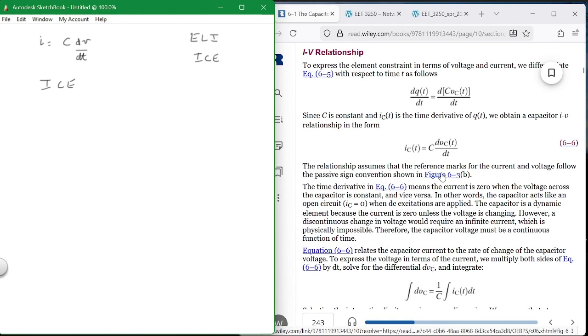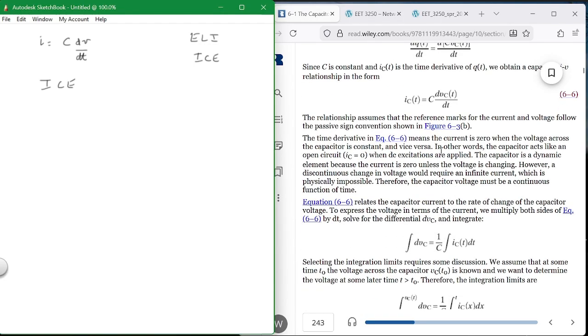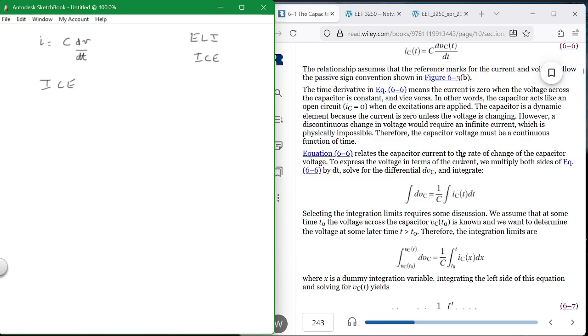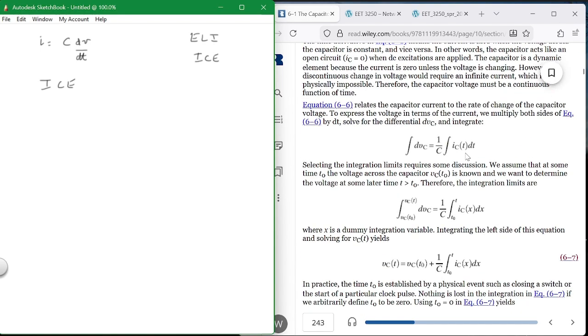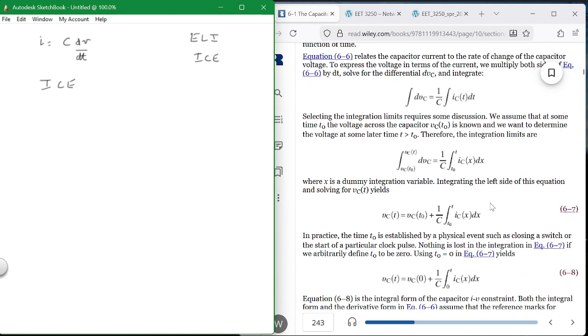So that gets you what? It tells you how you get current in a capacitor to pass through that device. You have to vary the voltage. And what kind of signals vary in voltage? Well, a sine wave does, obviously. So that's how you get a pass-through, even though you actually don't get passing through, you get them oscillating, store, unstore, store, and unstore, that type of thing. And the voltage is V equals 1 over C integral I dt plus the original V sub 0. So basically, this would be my integral formula.